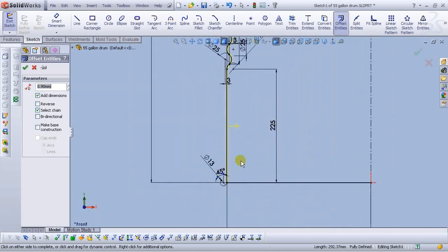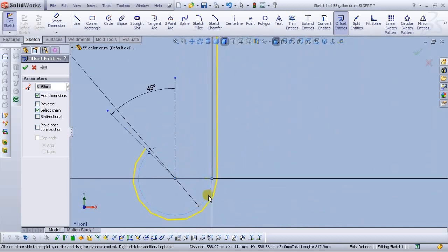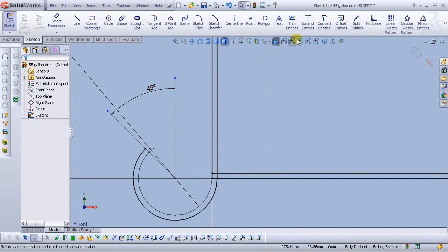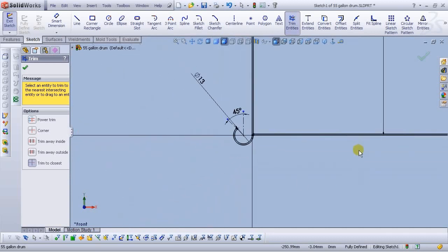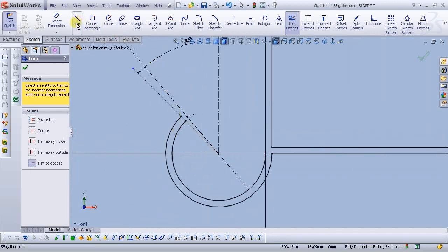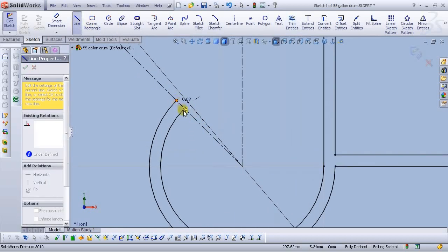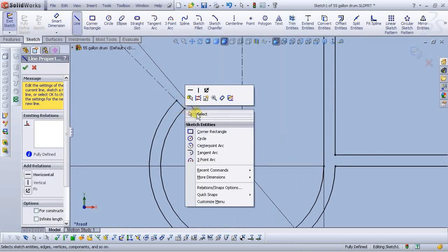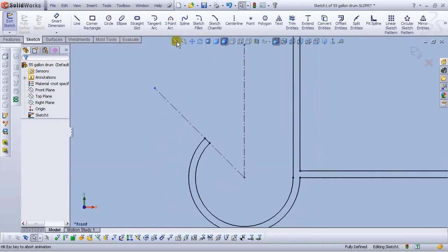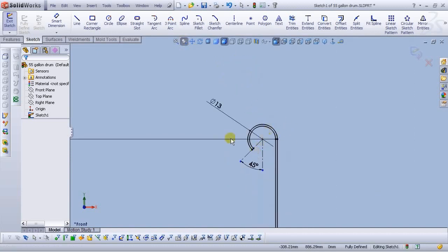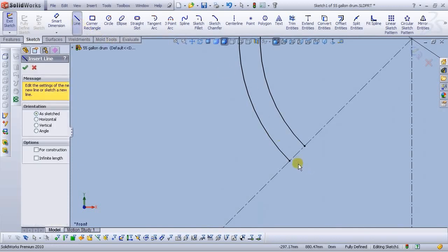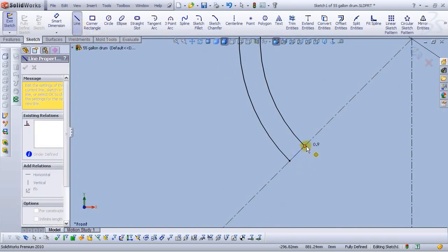Now let's make some offsets. Select the Offset tool and for the offset distance select 0.9 millimeters and let's say reverse direction. Uncheck reverse direction. Okay, now it looks good. Let's see it. Alright, right here. Select this line and this line here. Okay, then select OK.